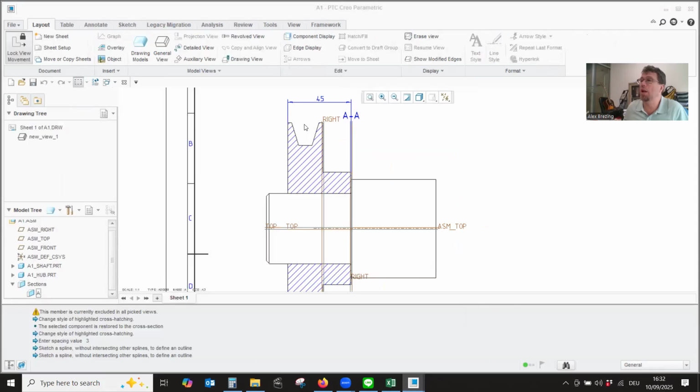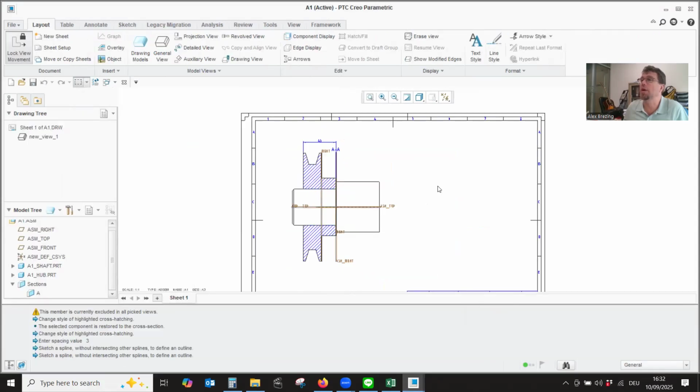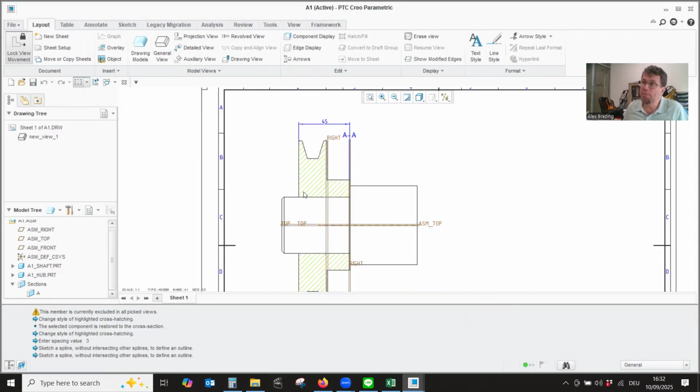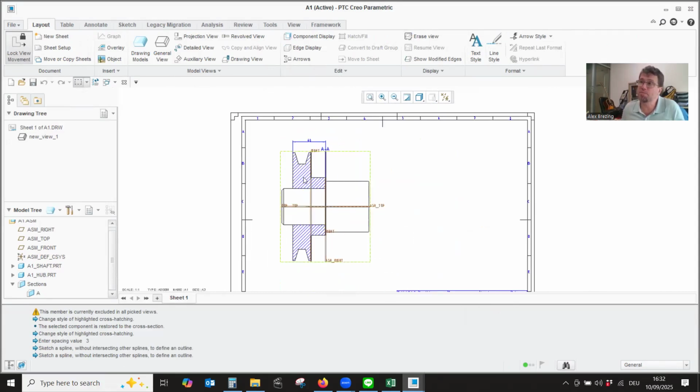And for now, all I have in the drawing is this, right? So a full section of this side view. And what is missing for your assignment is, of course, the design features for the feather key. Could be here, could be that. It's the same. And in order to show that, we need a local section here. Secondly, we might want to break this off here just to indicate that the shaft will go on in real life, but we're just interested in showing this bit.